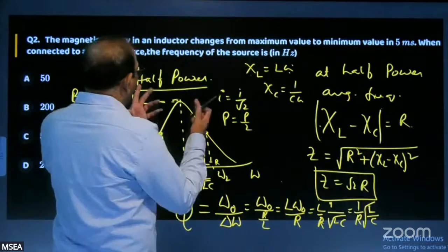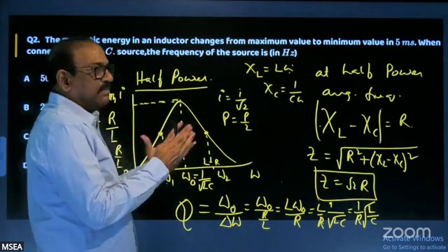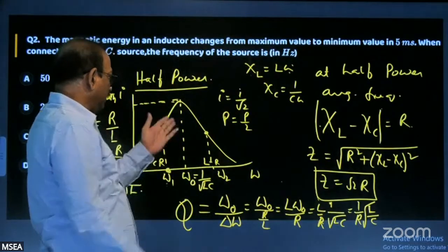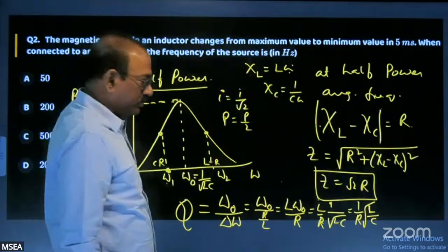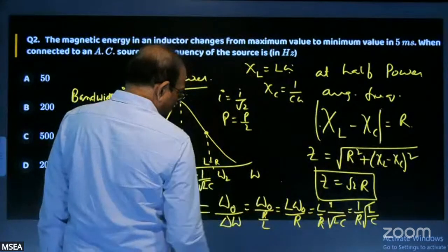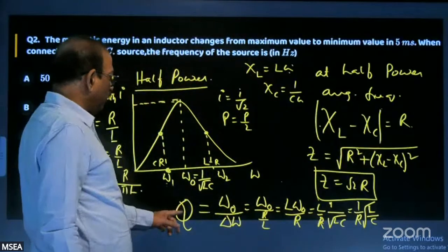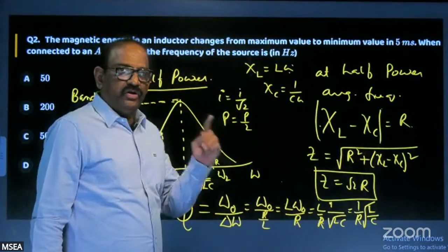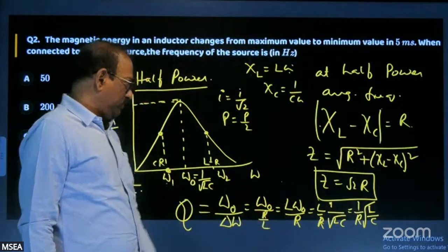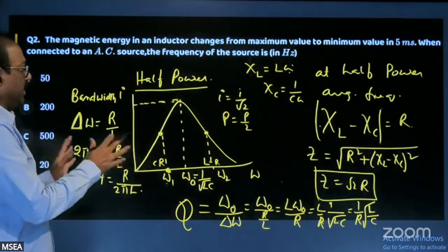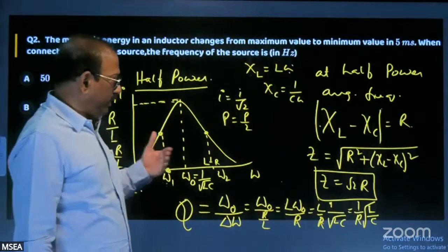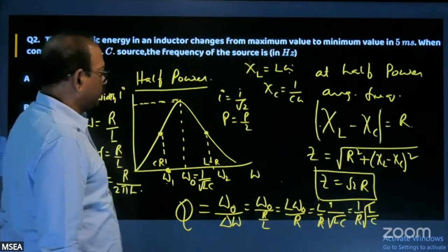If quality factor is more, the resonance is more sharp and the circuit is more selective. This you have learned; it is used in radio tuning circuits to match the frequencies. L should be more and R should be less to have more quality and more sharp resonance. These points, whatever I have discussed briefly now, you have to revise frequently in this chapter.